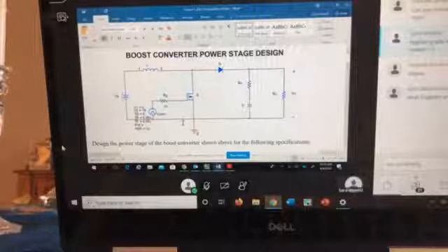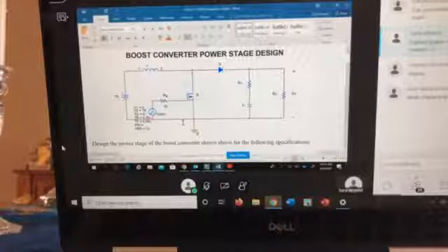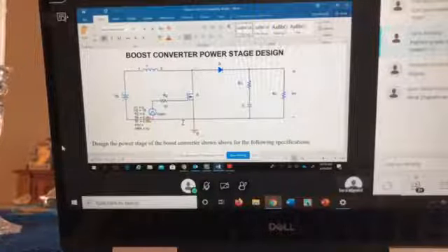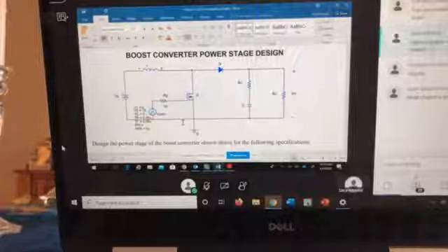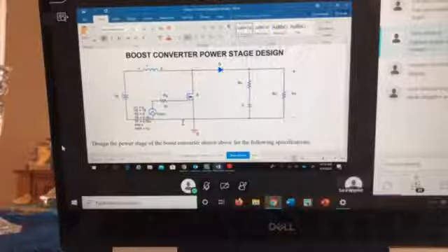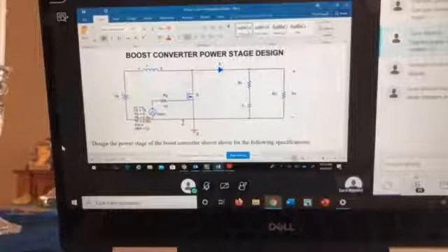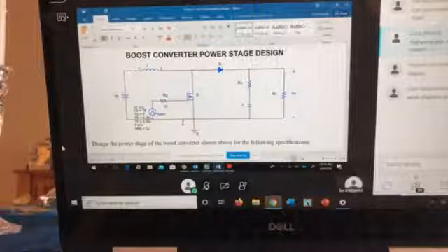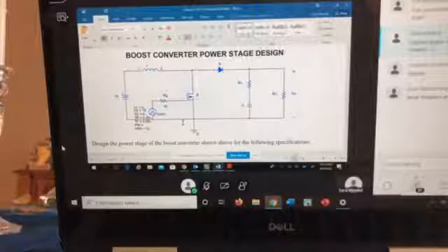One mistake that I saw in a couple of you is that, with all these different specification ranges that I'm giving, you are changing the L's and C's every time. And in the end, you don't choose one. You cannot do that. Imagine you are building a PCB with the components. Every time you change your operating condition, are you going to take off this capacitor and put another capacitor, take the inductance and put another inductance? You cannot do this. You have to design one converter that fits all, right?